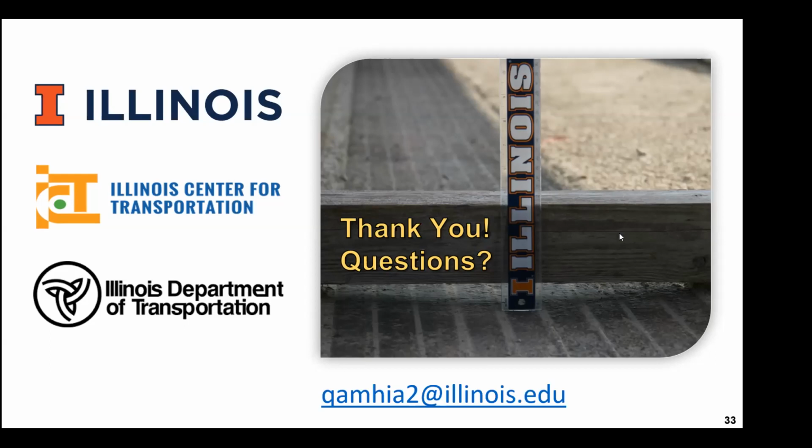I would like to just thank Isam for a great presentation, and I would like to add one point to what he has made very nicely, which is what we found over the years with testing dolomite in many different studies, including this, the third accelerated loading APT testing study, where we were able to finally study durability aspects of at least three winters of cementation and what we call this dissolution precipitate kind of chemical reaction effect on the dolomite's durability results.